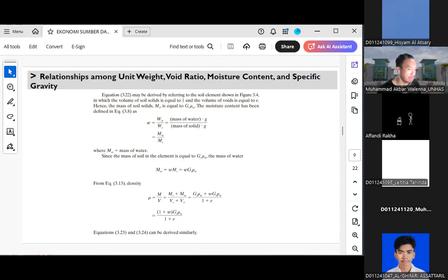Higher moisture content means the amount of water is higher. In civil engineering, if the soil contains more water, it is heavier. For example, in designing a slope, if the soil is heavier and contains more water, the potential for failure of that slope is higher, because adding more water adds more weight, which increases the driving forces for the slope to fail.